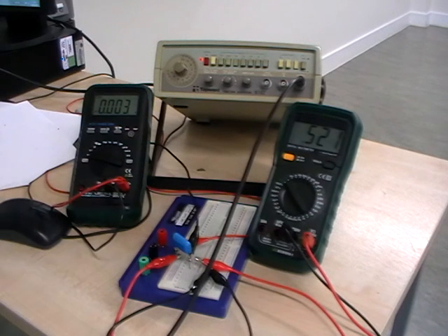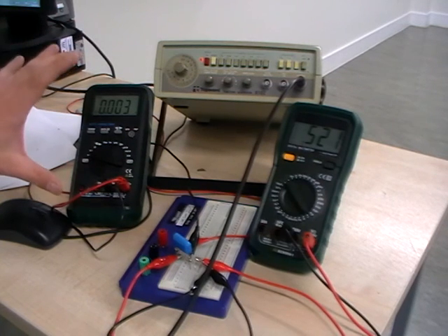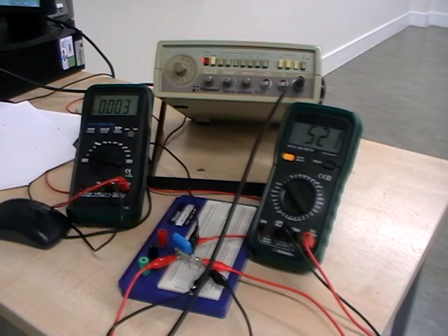One thing I have to say though is I'm not quite sure how these meters are configured. They're normally configured to operate at 50 hertz, so going up to about 20 kilohertz is pushing it a little bit with these meters. Also, the signal generator is not putting out the full power. What I should be doing is using a scope, but it gets a bit messy interpreting all the traces on a scope, and here we've just got numbers, which is easier to trace through. We are losing a little bit of our signal because of the way the digital meters are set up, but the main thing is we are looking for the ratio of the voltage drops between our resistor and our capacitor.